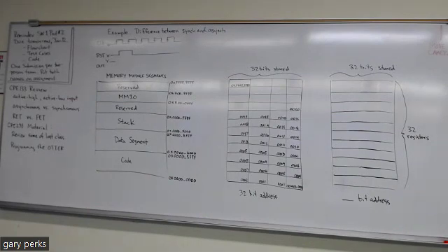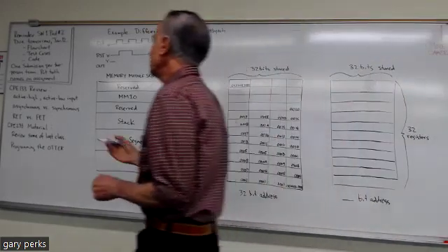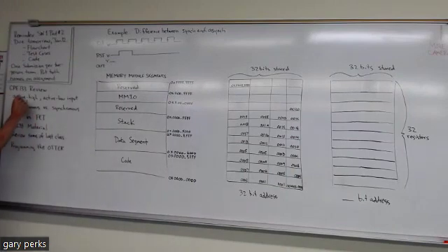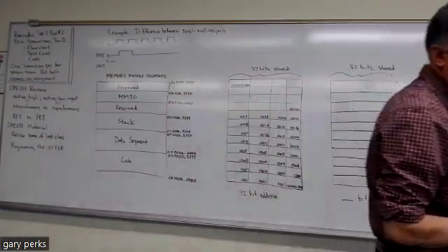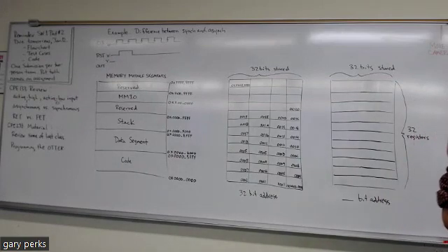Yeah, exactly. It just means that when you make that input a 1, whatever that input is, like if it's a reset input, it's going to reset, right? And if it's active low, it takes a 0 to make that input happen. So active high, it takes a 1. Active low, it takes a 0. Now, in this class, all the inputs of the otter are active high. Okay, so you'll see when you start building the otter, all the resets are active high, all the loads are active high. Okay, so everything for your otter is active high.